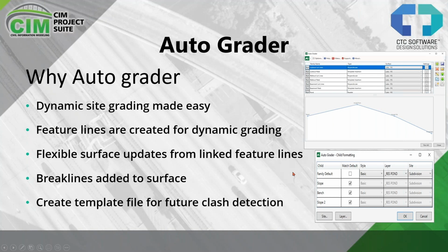The break lines get added automatically. That's what it does. That's a powerful tool for site grading. Many of you are probably already doing your sites with break lines, so this puts them right in there for you, giving you lots of flexibility.